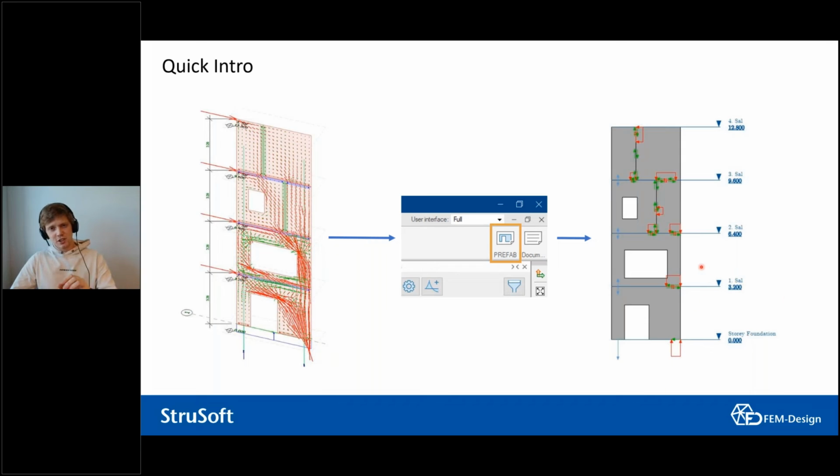This is an elevation. You can get it as story plots instead, however way you like it. It's an interactive PDF, so you can click on stuff and get information. There are also tables there, so you don't have to click for it, but it's interactive, it's intuitive, and it's very easy to understand the load takedown.